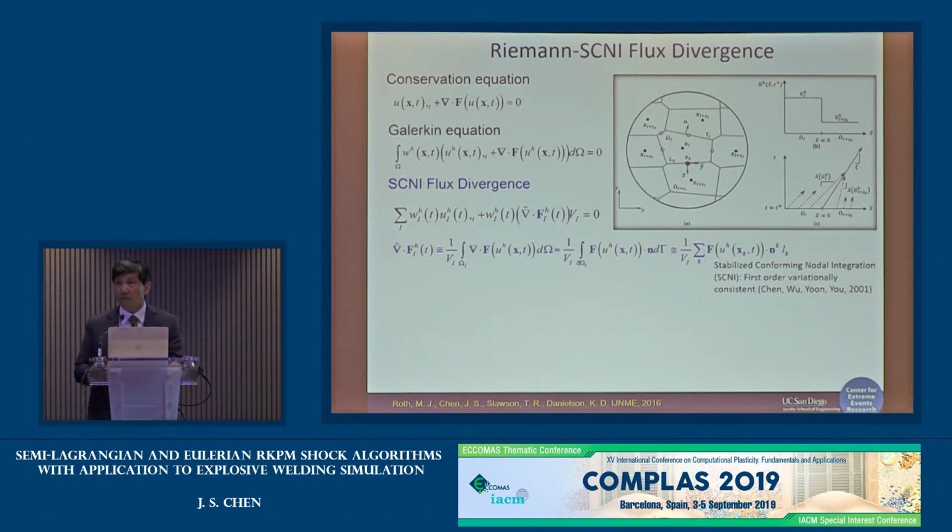So here the variational consistency refers to the consistency between the order of completeness in the approximation and the order of exactness of the Eulerian solution. That means that if I use linear basis, such as linear finite elements, I have first order completeness. I want to make sure that the Eulerian solution is exact up to the first order, and that's our standard patch test, the linear patch test. If I have linear finite elements, regardless of the element shape, I would like to get an exact solution for a PDE where the solution is first order. And that's where you can define all those patch test problems. So we call that the first order variational consistency.